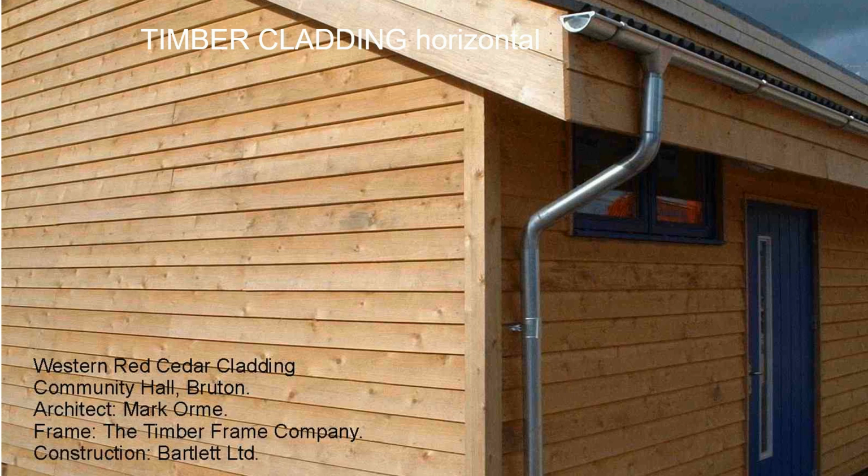So if we look at an example of a durable timber cladding, this is a horizontal timber cladding. It's a Western red cedar, which is a kind of orangey brown colour. You can see there's quite a lot of knots in it. And the way that this timber has been put onto the wall is there will be vertical battens behind that, because you've got to fix every board in the same place.